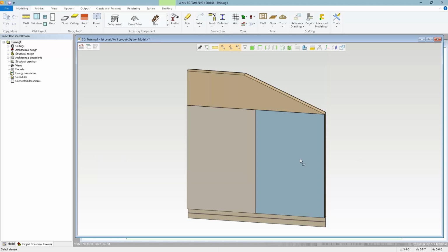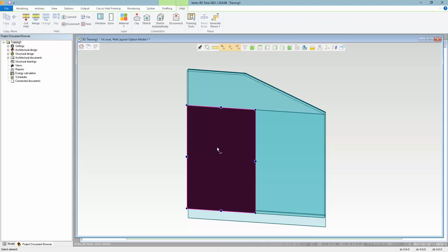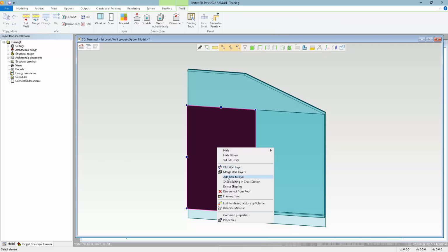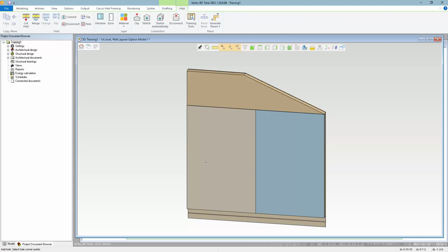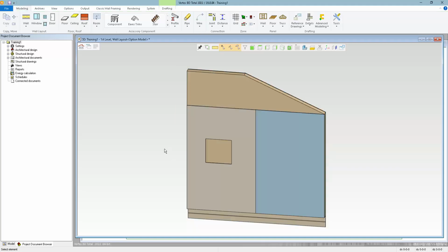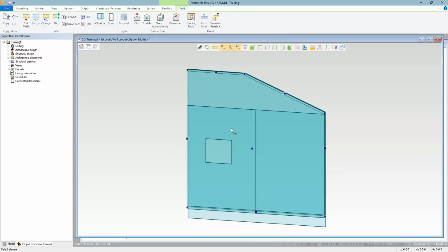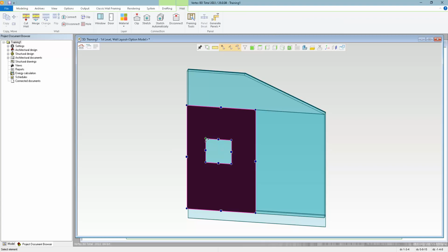We also have the ability to cut a hole in just one layer. Here I'll just click two opposite corners of a rectangle to define a rectangular hole. Now when I select that layer, I get additional grips and grab points around the hole, so I can adjust the size of the hole.